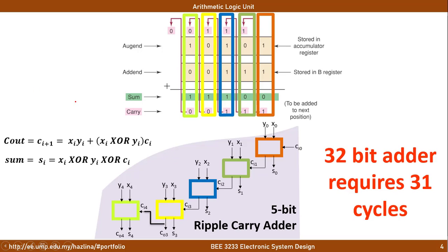In the previous example, we denoted this as c in or c out and continued through. Note that there is an addition that is being mentioned here as i+1, which means that the next bit is for this c out. And this is for the current sum properties. So this addition can be simplified into these two equations as a general representation for the ripple carry adder.